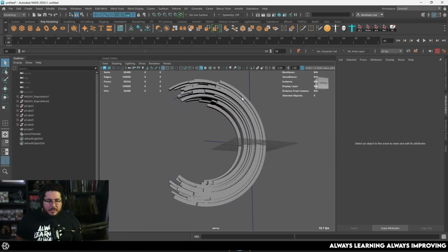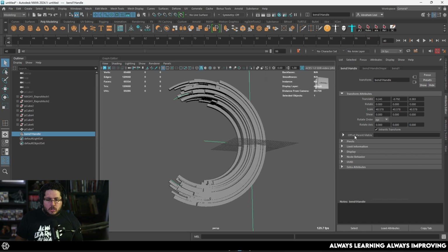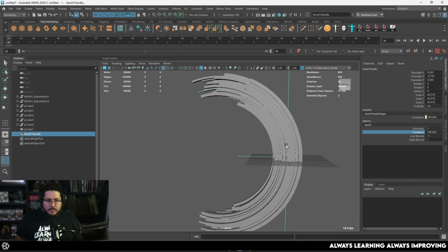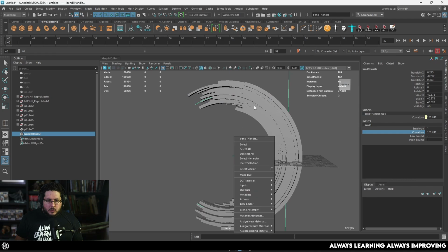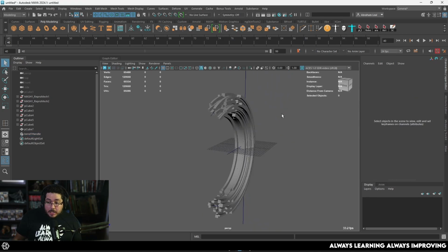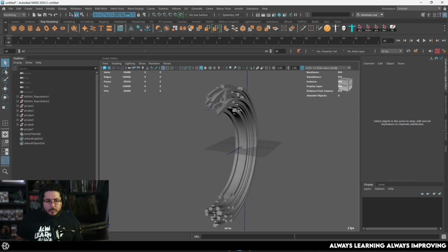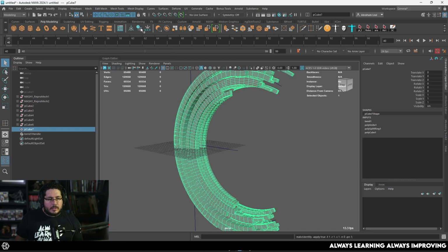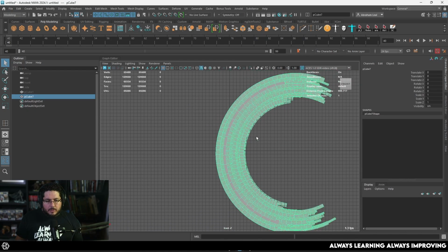And even though it's going to be a little bit tricky to print, it shouldn't be that much of an issue. That's one of the big advantages of resin 3D printing: the fact that you get access to being able to print shapes that, at least traditionally with FDM or with filament, is not as easy. So once we're happy here, I'm going to delete history, freeze transformation, so that we get rid of the modifier.